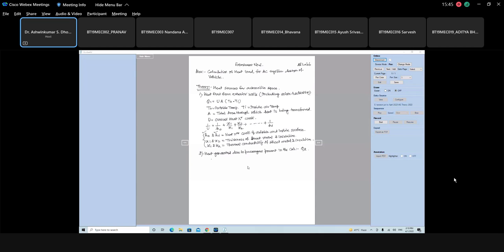More or less, this Q2 is equal to 334.4 kilojoule per hour. This is basically the average value per person, so you can multiply and get the value. The human body is considered as an engine which converts thermal energy into mechanical work with a thermal efficiency of 20%. Okay. So this is the average value you can take.